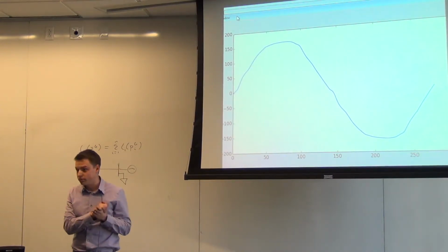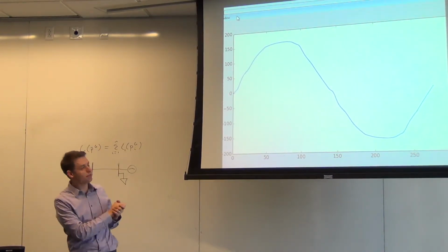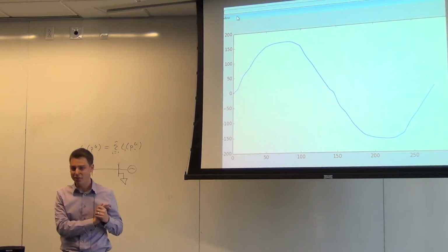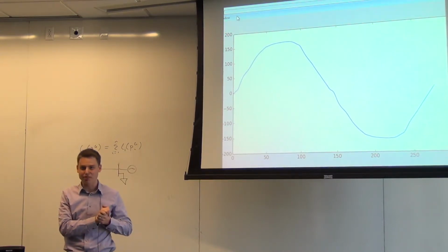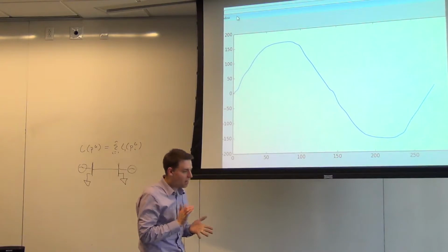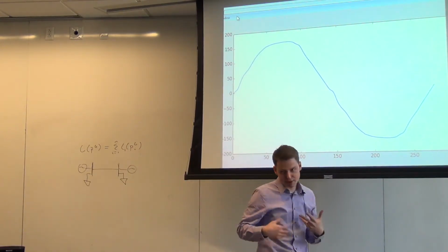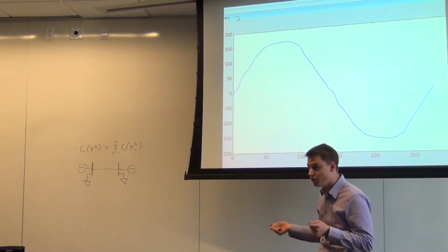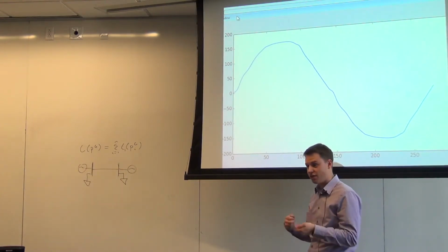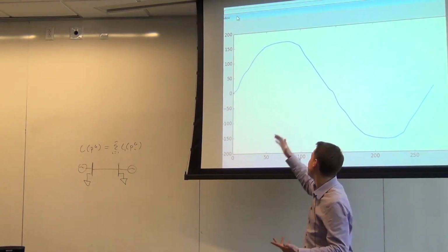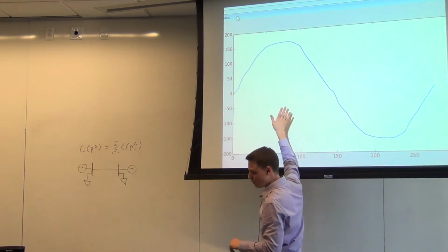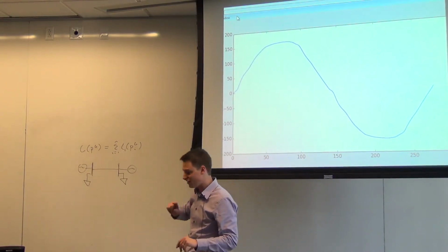This looks reasonable, right? This looks like what we expect. It's a little bit bumpy, actually. It's kind of weird. They're never actually that nice, the sine waves here. This is because big devices, especially big electronics, actually inject a little bit of noise in these signals, which corrupts the nice sine wave that you would normally see. And so there are little bumps here. But this is actually pretty good when you think about what we're about to see in a second when we talk about current.